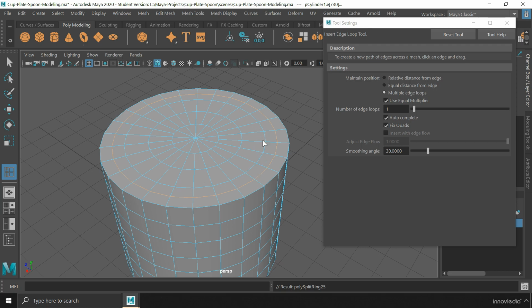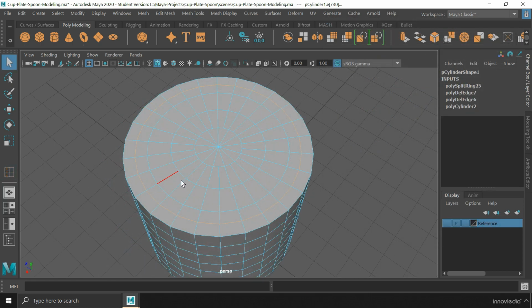And for that, I am going to select this entire area on top till here and extrude it down to create the hollow space. So, I am going to select all of these faces on top except for the last loop. To select these face loops, first you have to select a face. Hold down the Shift key and then double click on the adjacent face to select the loop in that particular direction. The second selection determines the direction in which the loop has to be selected.